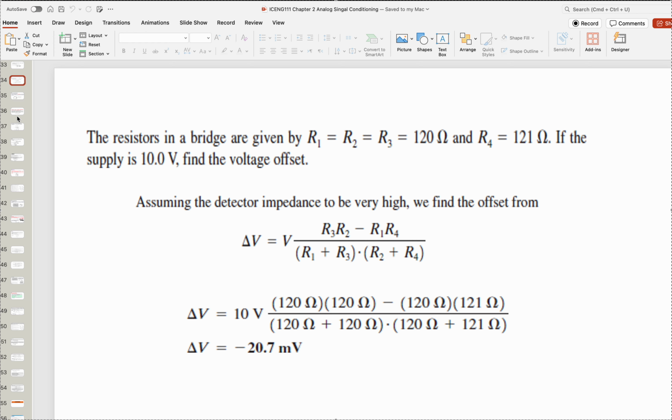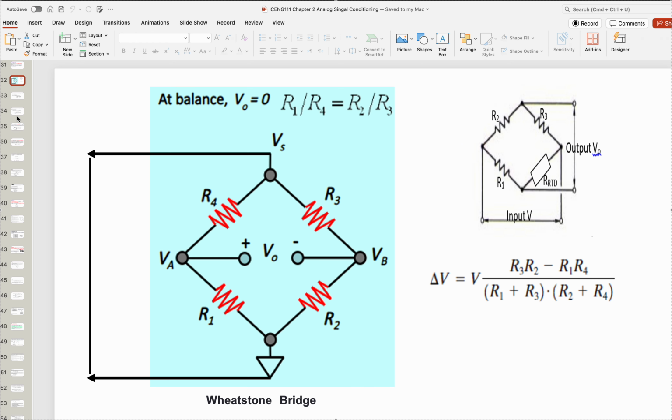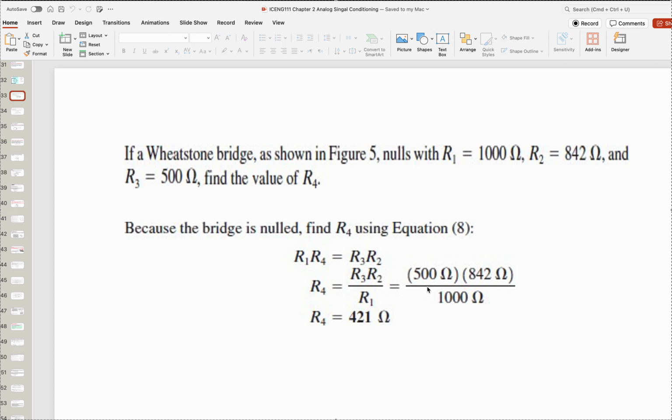So the Wheatstone bridge, this is the one that we have here, and that is the other form of equation, which is exactly like that one, just rearranging it in a different way. So if you have these 4 resistors, you're just substituting. Now take care that I'm going to tell you that the RTD changed, which makes this Wheatstone bridge unbalanced. When I say unbalanced, that means the null voltage is not equal to 0, as this delta V will be changing. Okay, so just consider that as one of the things that will be considered when we do our calculations.